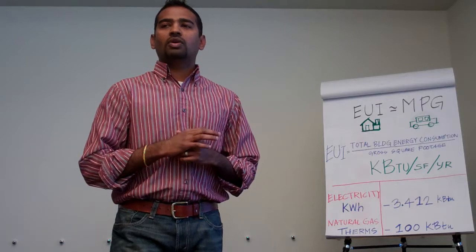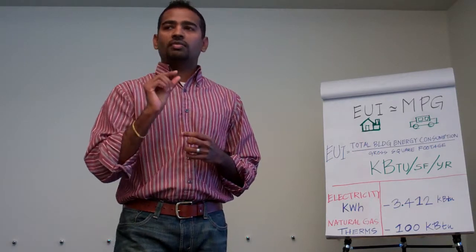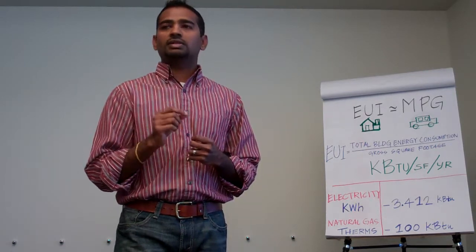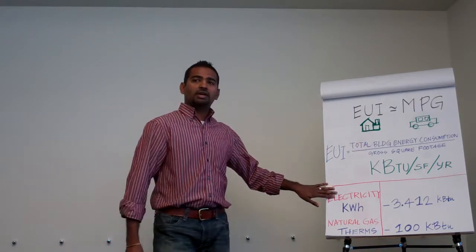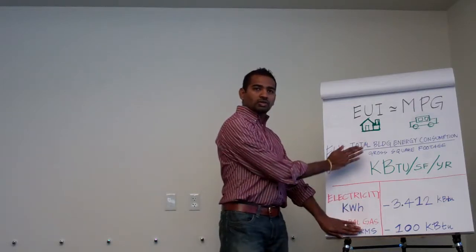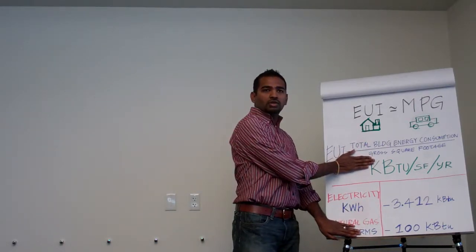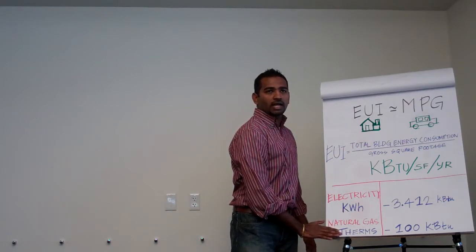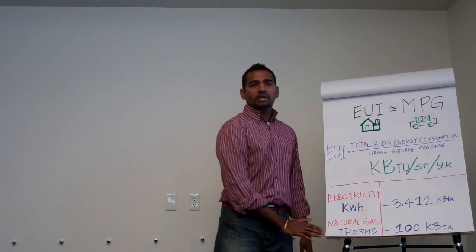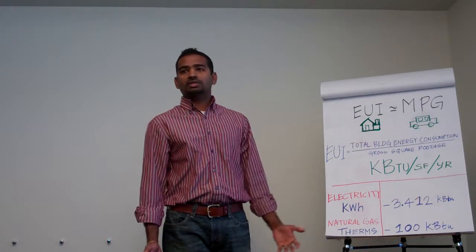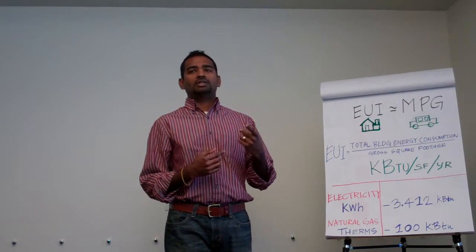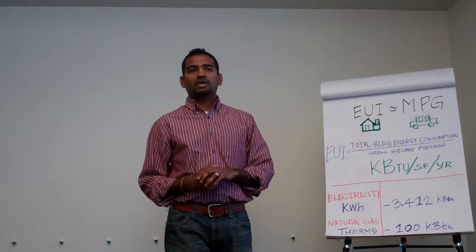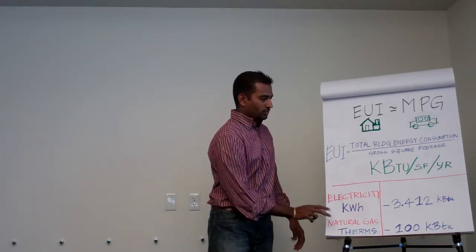Okay, and what is the unit of measure for the gas consumption? Therms, right? So if you just look at your SRP or APS bill, that's not telling your story entirely. Your kBTU also depends on your natural gas usage. So if someone asks you how much my house is consuming, what's the EUI of my house, if you have gas, you should add both. So we need to know these two numbers for sure.